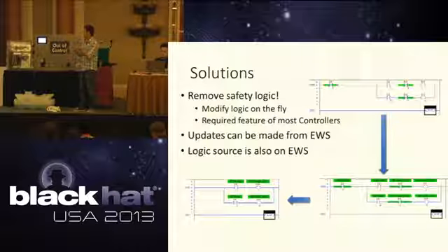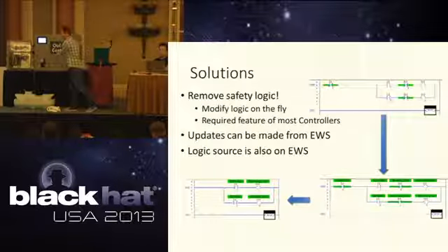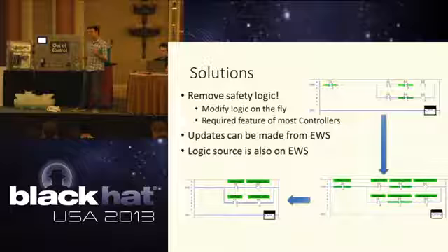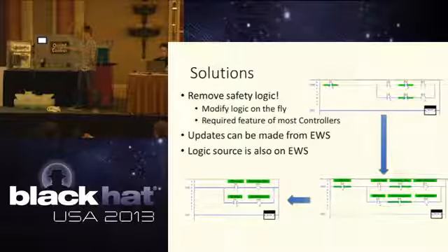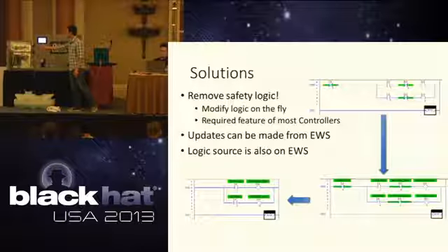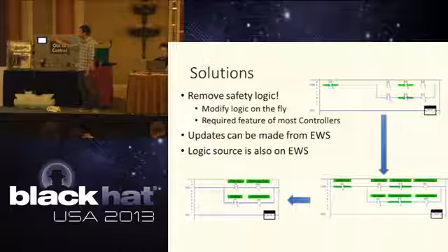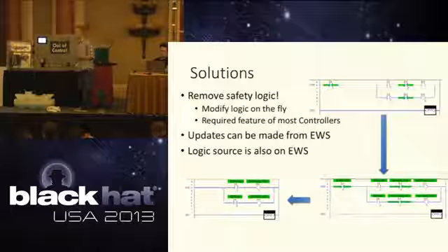So all you know is input 0 or output 0. You don't know what its actual mapping is, but you can see the control flow of how the controller is supposed to look. So you don't have to be on a Windows workstation to get a baseline of what is happening on this controller. But if you do, which we have down there in the bottom right, you can remove that safety logic. Over there on the very left-hand side, all we did was remove that overload.